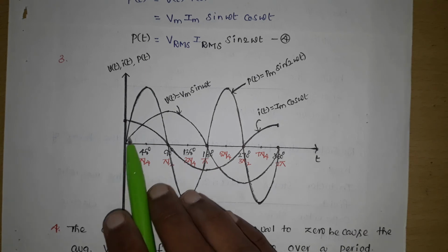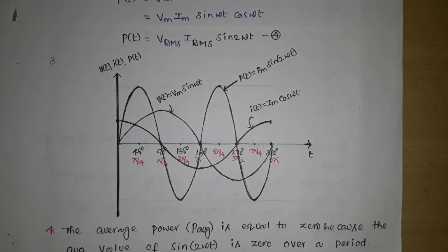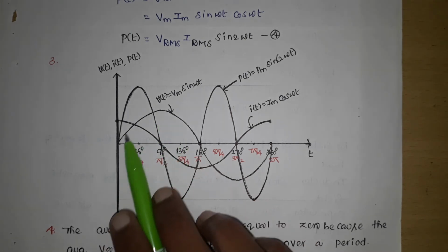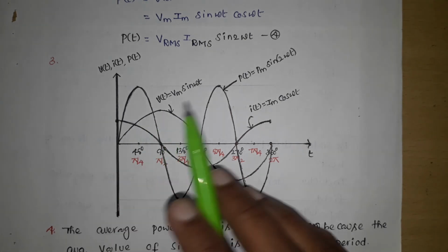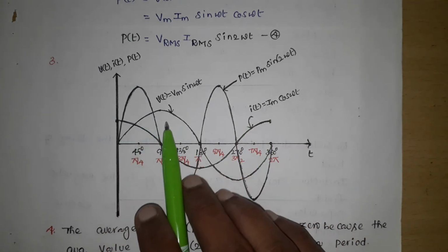During increase of the voltage, the capacitor always stores energy in the electrical field. As voltage is increasing, the electrical field is increasing. The capacitor has the capacity to store energy in the electrical field. So during this first quarter, as voltage is increasing, it has the capacity to increase the electrical field, and that's why it is taking power from the source.